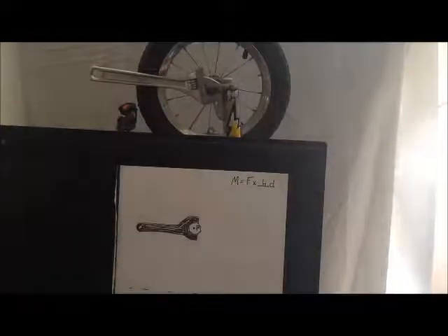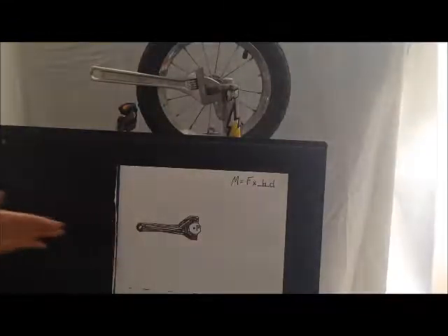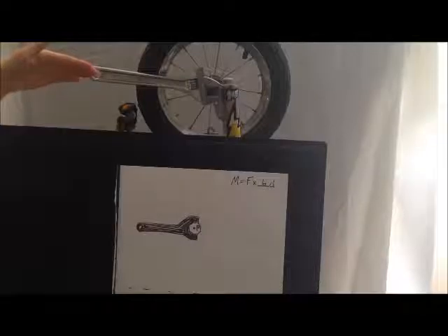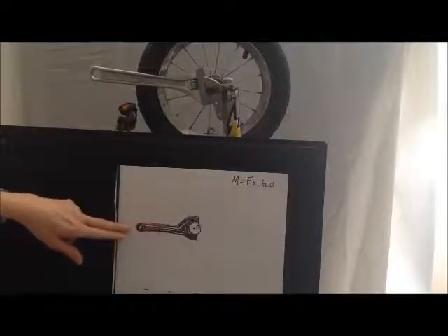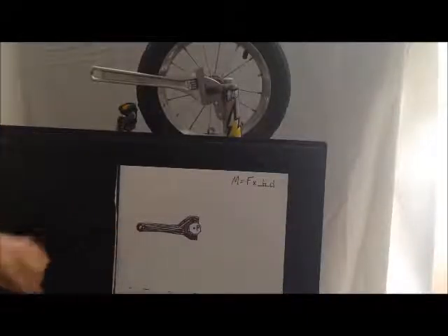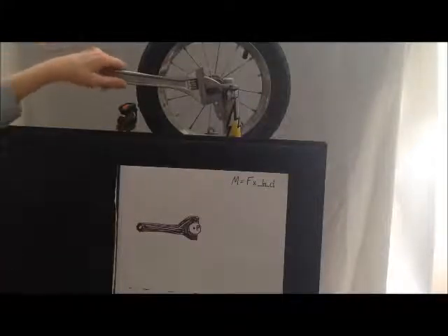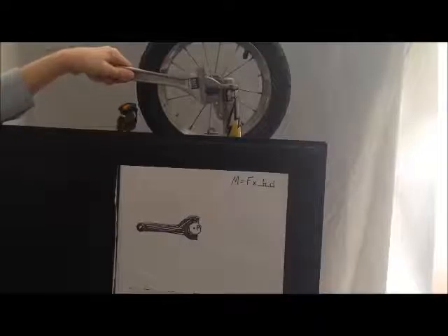So here we have a diagram of a physical system where we're going to show how, when you're pushing on a spanner in different ways, you can draw that diagrammatically and, with an oblique force, work out the components to work out a moment, and show a couple of different ways of working out the moment. Now remember that we said the moment is the twisting.